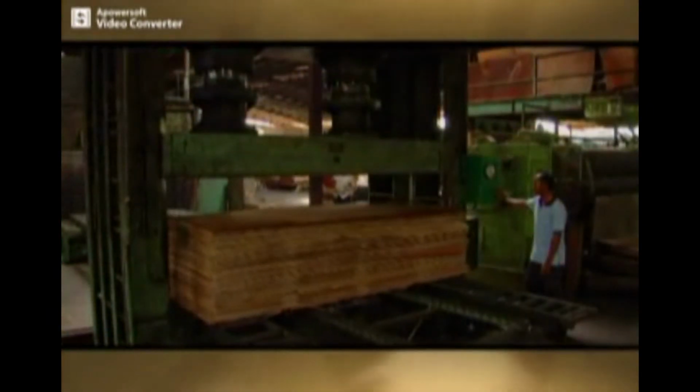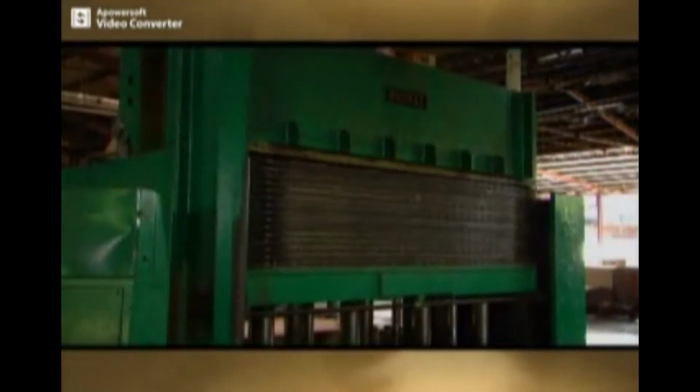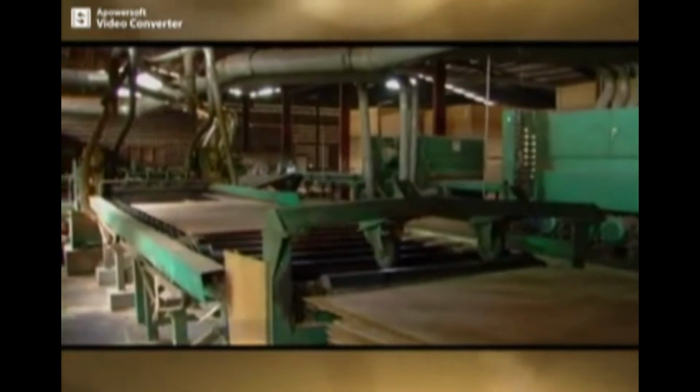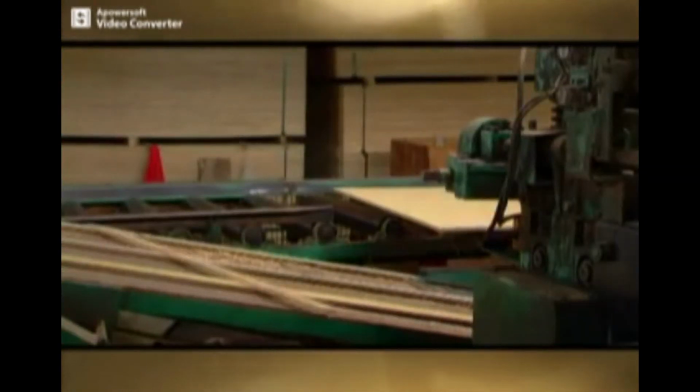Then, the laid-up veneers are transferred to the cold press to ensure that the adhesive is evenly spread. Finally, the pre-formed panels are fed into the hot press to complete the lamination process under preset conditions of high pressure and high temperature. The palm plywood panel is then edge trimmed to the required size and then sanded for a smooth surface finish.